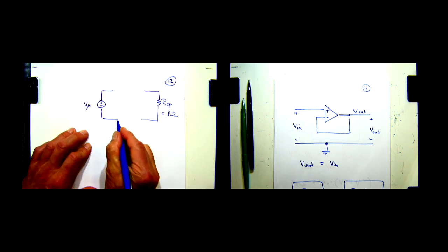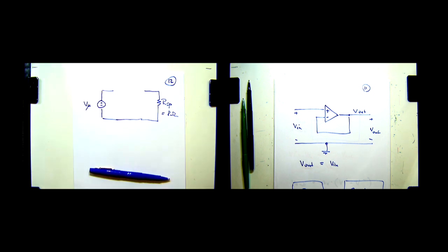Now you hook them together. But actually, the microphone, is this a reasonable model for the microphone? In other words, if the microphone output voltage is, let's say, 100 millivolts, can this microphone supply any current that you want to pull from it? Probably not, right? And so, have we developed some kind of a model?